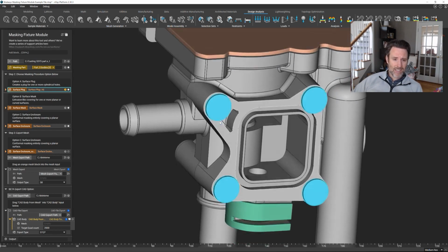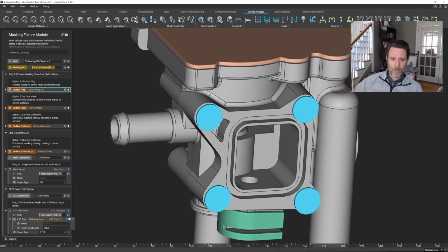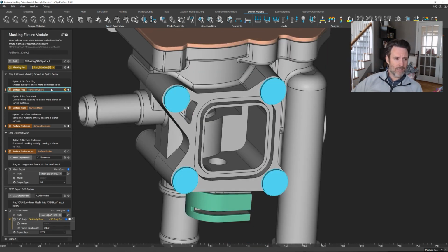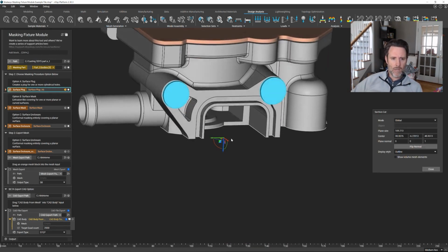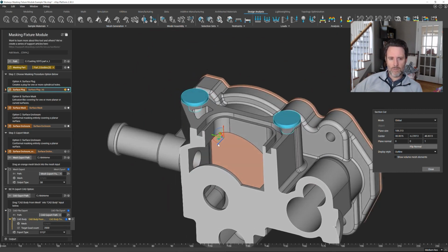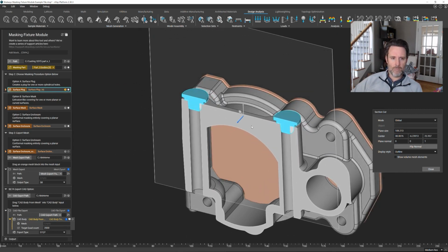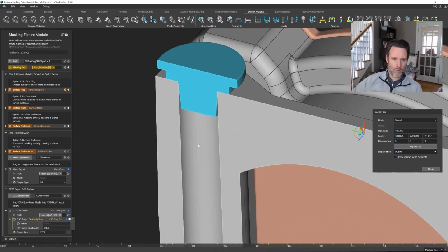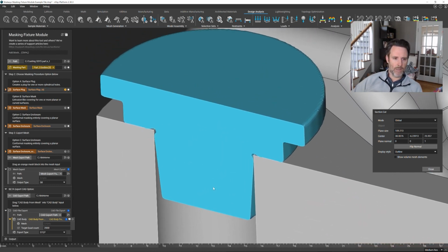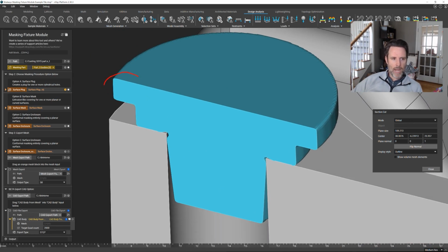The plugs do exactly what they sound like. They plug holes on one or more faces. There's a couple interesting things that I want to draw your attention to, and we put a lot of work into this module making sure that it was meeting customer requirements, but that it did more than just stick a plug on a hole. So three things in particular I want to draw your attention to. One, we automatically put some grips at the top. That's an option that you can check when you're creating it. So it adds a grip so it's easier to remove and insert the plug for that matter.